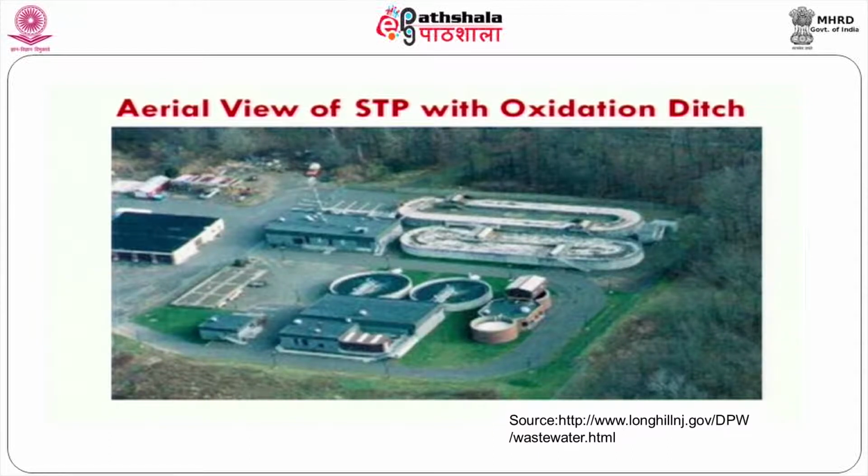By incorporating oxidation ditch as a secondary treatment unit, here no need to provide primary clarifier. The pre-treated effluent can be directly loaded into biological system. Subsequently, we have secondary settler. With the help of this secondary settler, we can segregate biological mass.